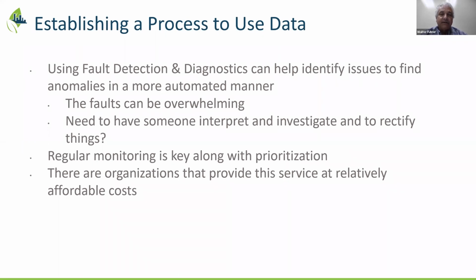And one of the things in fault detection that has been coming forward is what's known as people counting. As opposed to, say, you're monitoring CO2 and volatile particulate, et cetera, in a room, and you have a meeting, and now the ppm has hit that 1,000, 1,200 level, and now the VFD HVAC goes into full mode. Well, all of a sudden the meeting's empty and there's no one in the room anymore. So it kind of defeats that purpose.